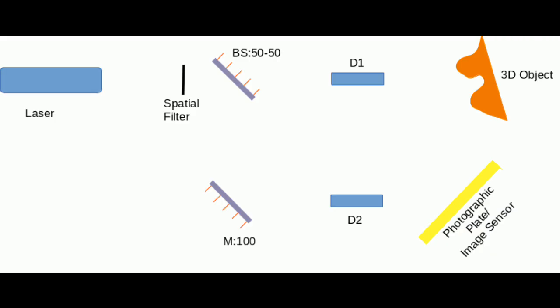An optical table is nothing more than a heavy steel table on which it is possible to mount and fix optical components. Some top-end tables will have a damper mechanism. The damper mechanism helps reduce extraneous vibrations from reaching the optical components. I've put a link below this video to a typical example of an optical table.